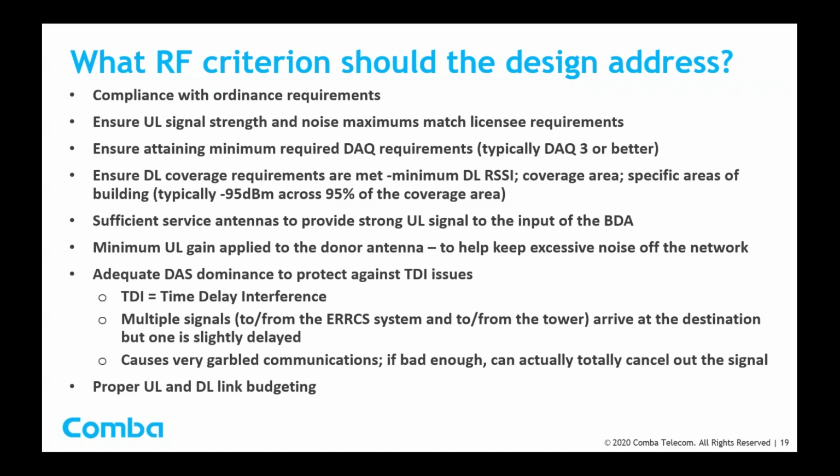If it's bad enough, it can actually totally cancel out the signal. So again, adequate DAS dominance, very, very important. We learned this many, many years ago in cellular DAS designs, because the same thing applies to a cellular DAS design. The other thing that the RF design should address is to make sure there's proper uplink and downlink link budgeting.